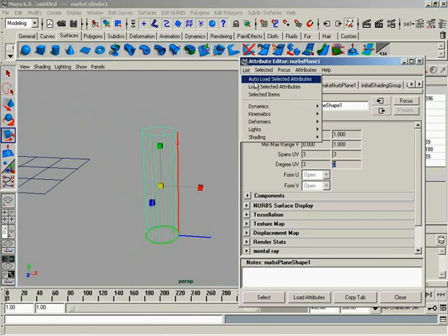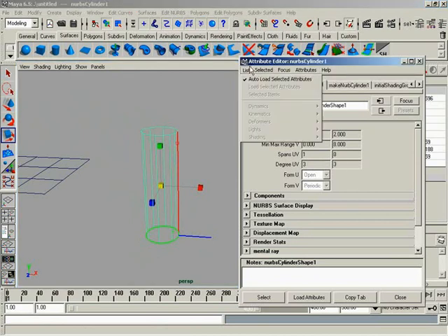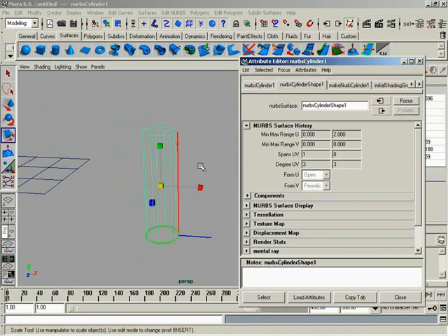Wait a minute. Hang on. Let's do that. We're still seeing it as 3 and 3, but remember, you turn this off up here. Be careful, because it's not going to reload when you click on it. And my job right now is to try to throw out as much information as I can quickly. But it's still the same thing. It's still 3 and 3. But we could have it where it's set to 1 and 3 if we wanted to construct something like this ourselves. And it's absolutely no problem whatsoever to Maya. You can also see here our spans U and V. This really makes sense. Our spans in the U direction, which is running this way, is just 1. And it is.